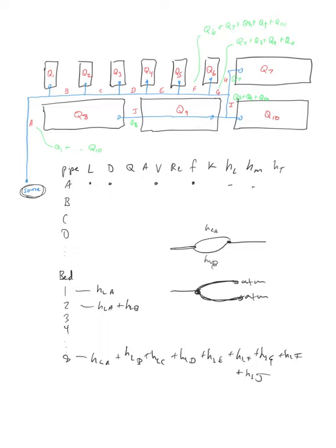What does that mean? Well, if I look at the schematic up here, technically the flow is going to distribute itself so that the head loss along this pipeline to Q1 is the same as the head loss all the way around to Q8.